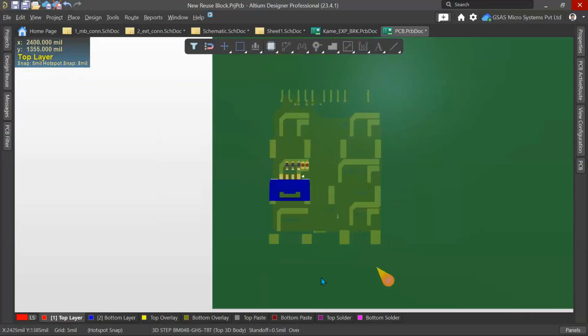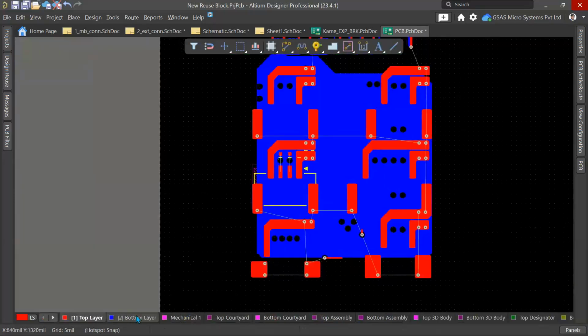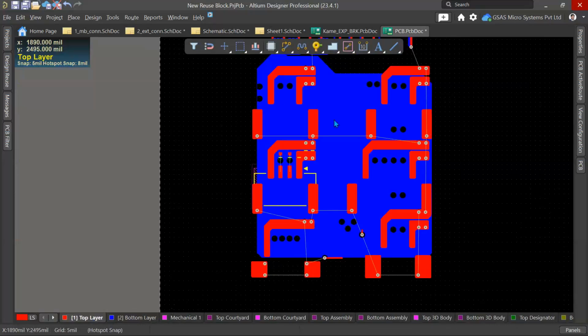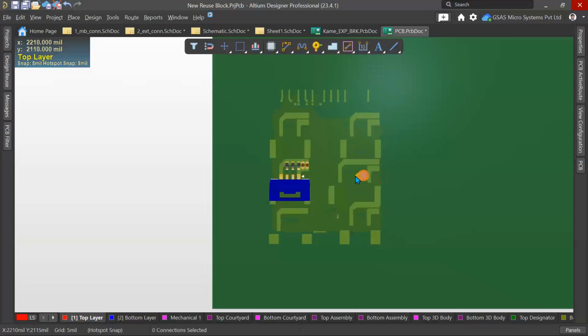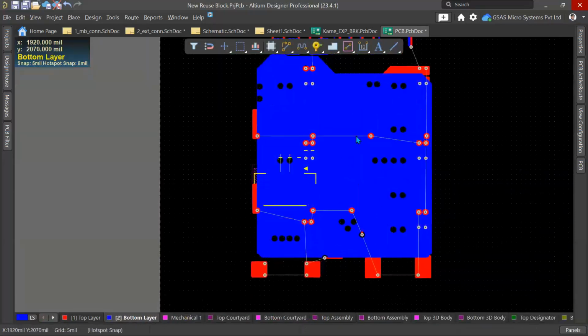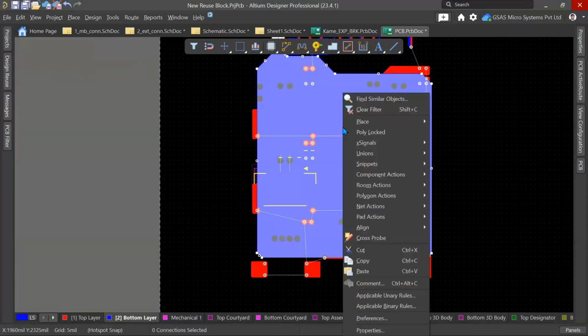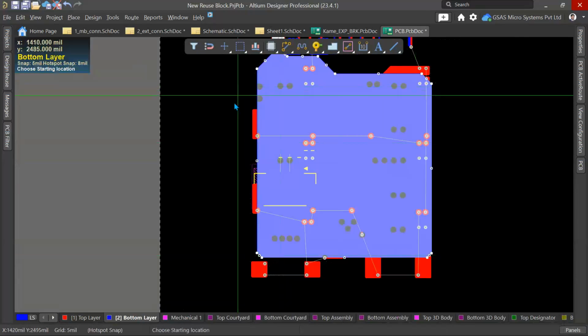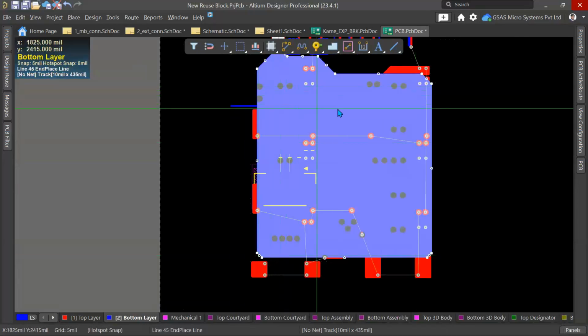and we don't want the other portion. We need to remove it, and also we need to trim the polygon which we don't require. This portion only of the polygon is required. Rest all we don't require. Let us trim the polygon by using the slice polygon option available inside the RTM. Just right mouse click once the polygon is selected and go to polygon selections and click on slice polygon part and just start slicing it out.